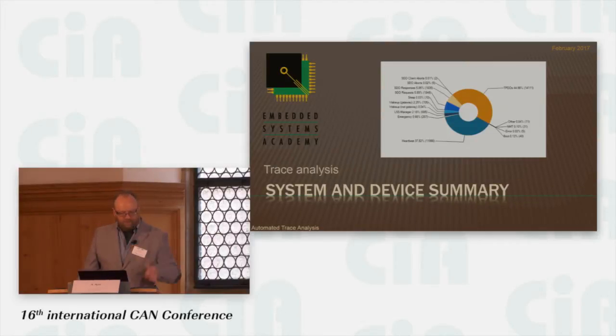The nice thing is, once you start collecting all this analysis data, you of course can also use various graphics to give you an overview. Where does my entire communication and bandwidth go to? And sometimes it's surprising what kind of graphics you get when looking at trace recordings. I, for myself, was most surprised to see that in the 447 system we looked at, almost a third of the communication on average came from heartbeats.